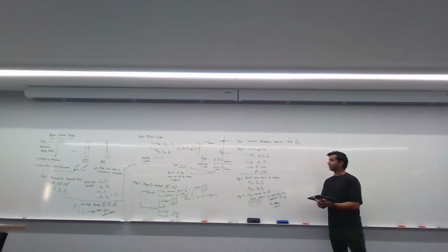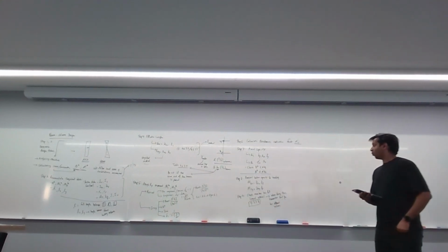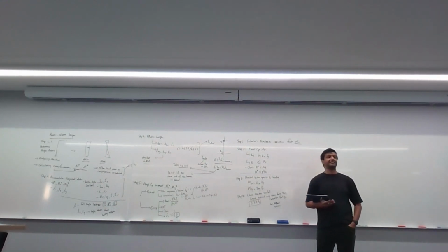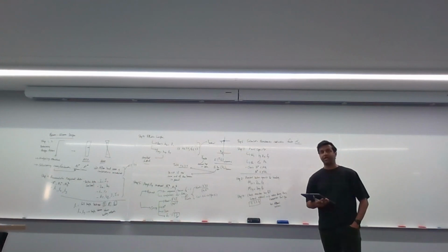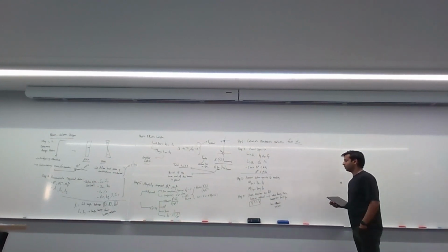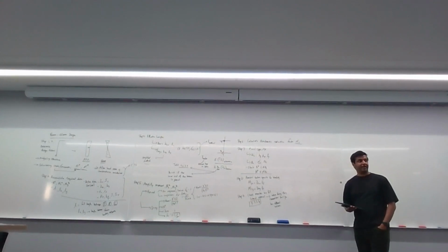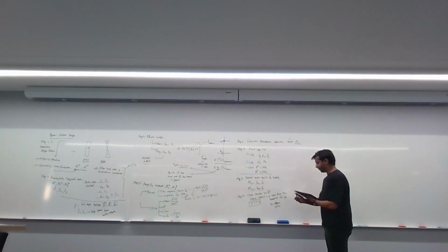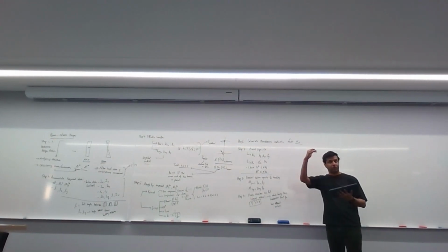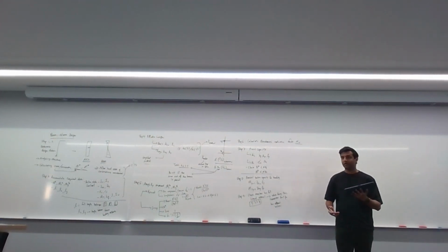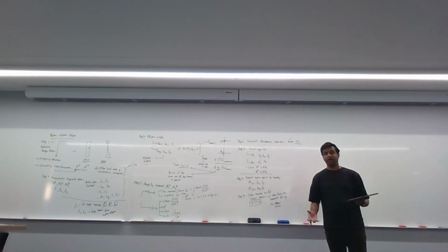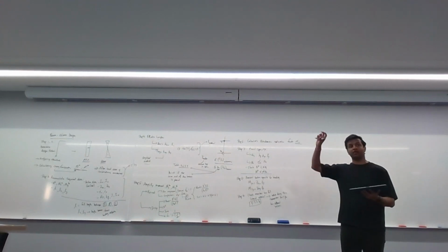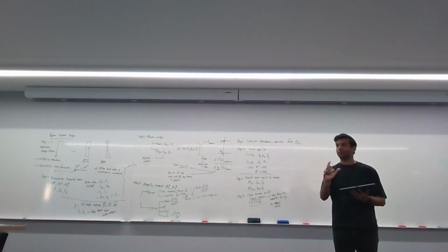One important thing to note when you are checking for full lateral restraint is there's a value for beta M that you need to calculate. Note that beta M actually has different values. For example, for segments that have only transverse loading, beta M is equal to negative 0.8. A possible beta M value is also negative 1. Another possible value is the ratio of the smaller moment at the top to the larger moment at the bottom.